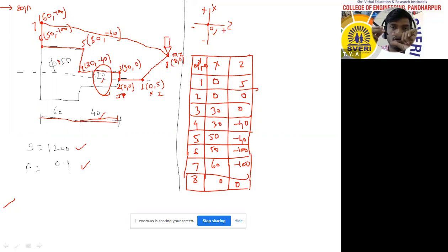And your component is rotated about 360 degrees, and your tool is fixed. The tool tip is touching the whole part periphery. So your tool is covering all 530 diameter, not only 515.